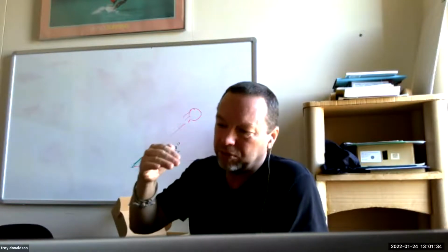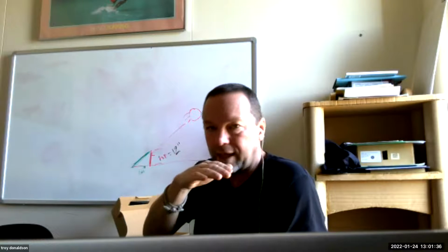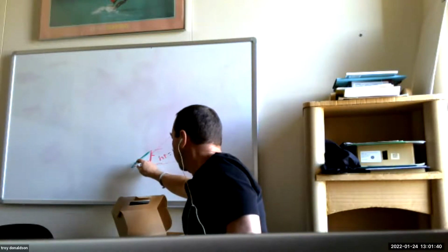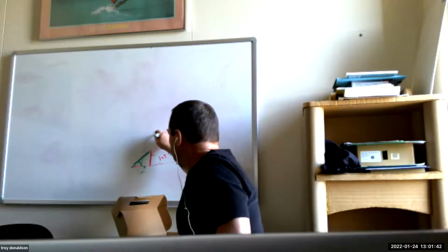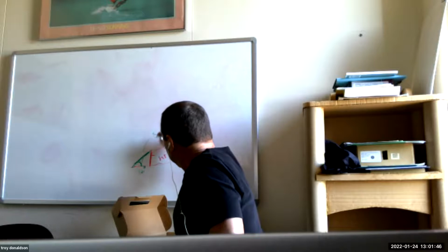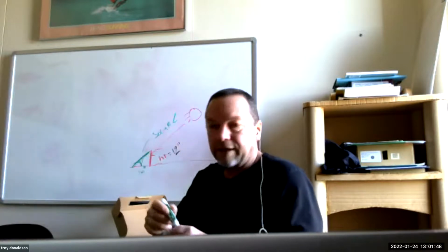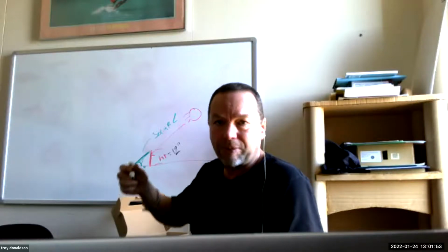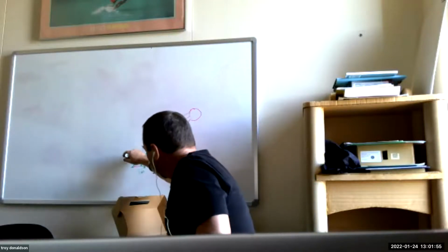That's the angle between the sun ray and the horizontal surface that you're standing on. So we're going to call this the solar angle, right? Now, it's not the angle we would set the solar panel to. The solar panel we would want set perpendicular to, so that is going to get set at a different angle. But all you're going to calculate is the solar angle.